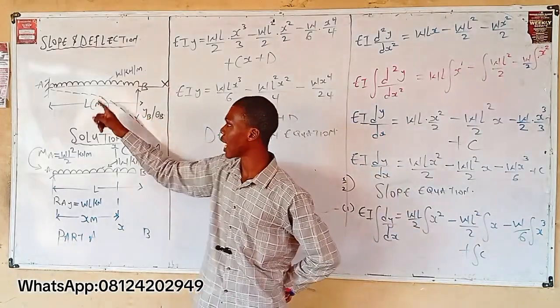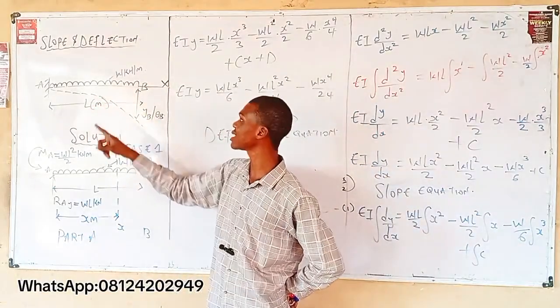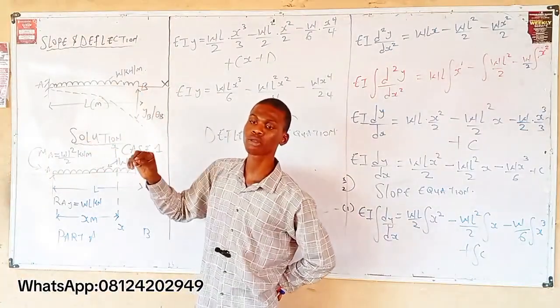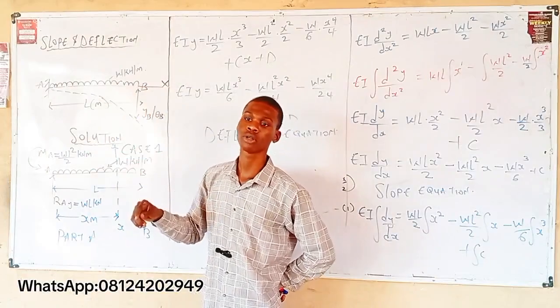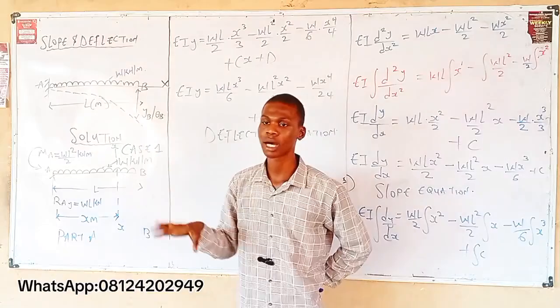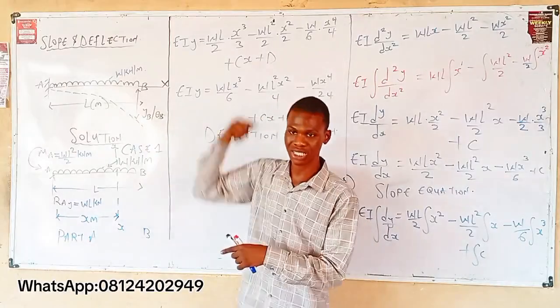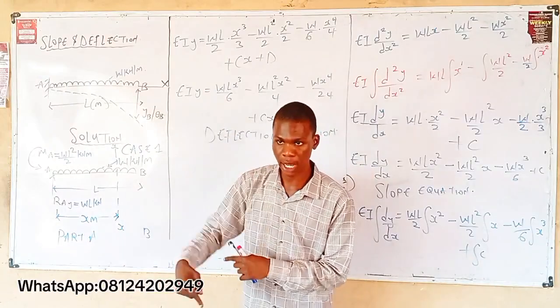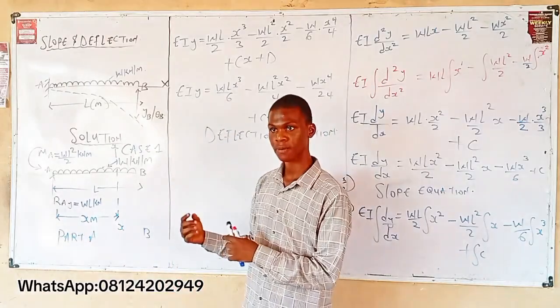What if this cantilever beam is loaded with another point load, let's say two point loads? It becomes Macaulay method, meaning it does not have a constant formula to use. You really want to derive the formula using these steps.